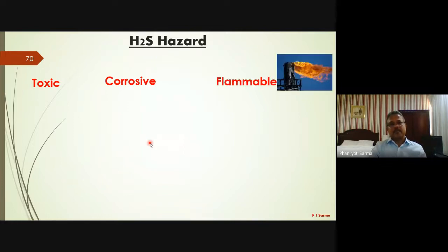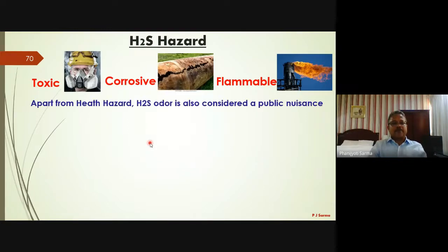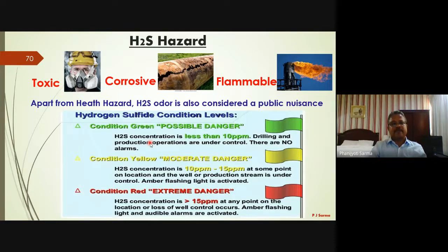If you burn the H2S, a more toxic fluid is generated, which is sulfur dioxide. So apart from health hazard, H2S is also an odor hazard. It creates a lot of public nuisance. So less than 10 ppm is a green condition. You can work up to 8 hours with a possible danger. 10 ppm to 15 ppm about 2 hours, and beyond that it is really dangerous.